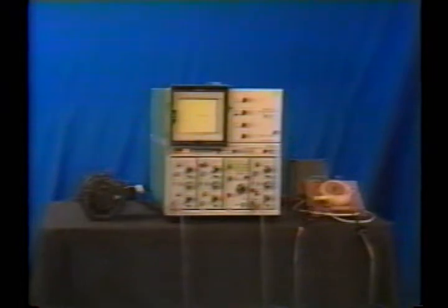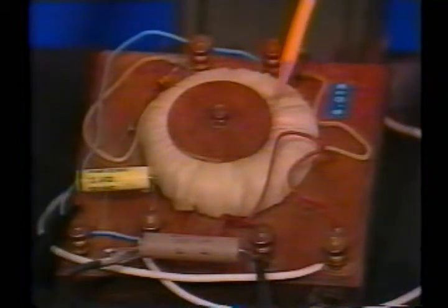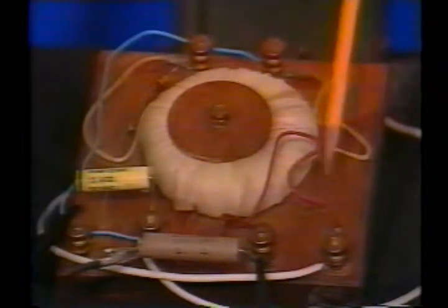Here is the experiment. The magnetizable material is in this donut-shaped toroid. The excitation or primary coil connected to these terminals is driven by the current at 60 Hertz from this variac. The voltage across this series 1 ohm resistance then gives a horizontal deflection of the oscilloscope proportional to I and thus H. The terminals of the sensing coil are connected through the integrating network with resistance 100 k ohms and capacitance 1 microfarad to the vertical deflection terminals of the oscilloscope. Thus, the vertical deflection is proportional to the integral of the terminal voltage, the flux lambda, and hence to B.